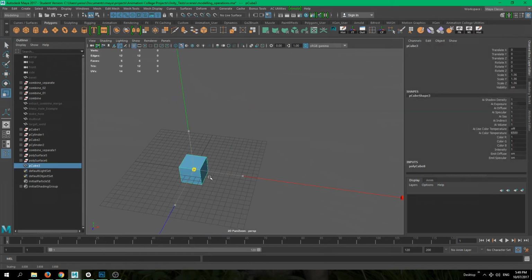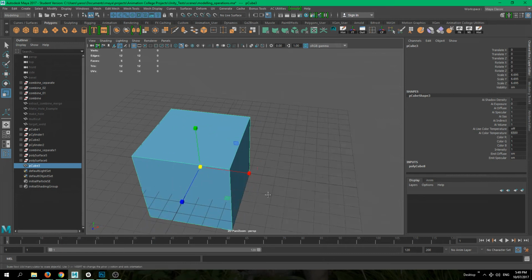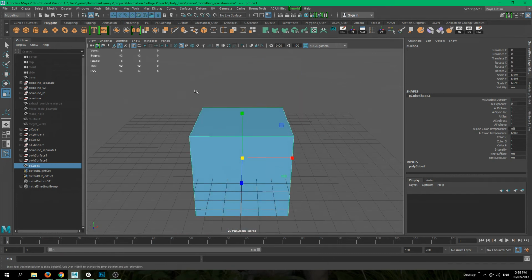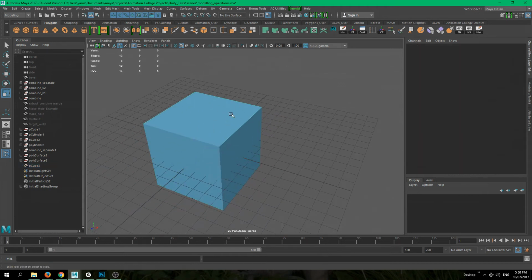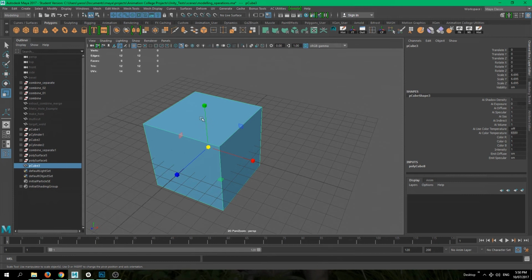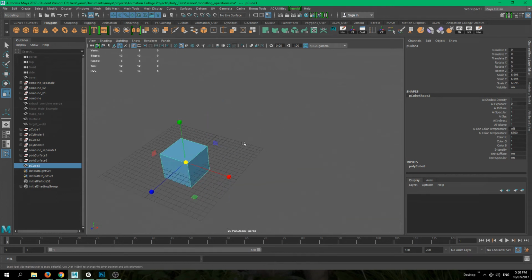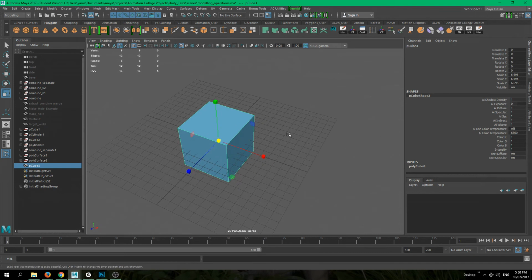So now we'll take a look at the wedge operation, which sort of allows us to create a nice little arc going between two elements selected. So it works with multiple components. We will have to have a face selected and an edge. So the edge will be kind of like the pivot point of the arc. But I'll show you how to do it really quickly.